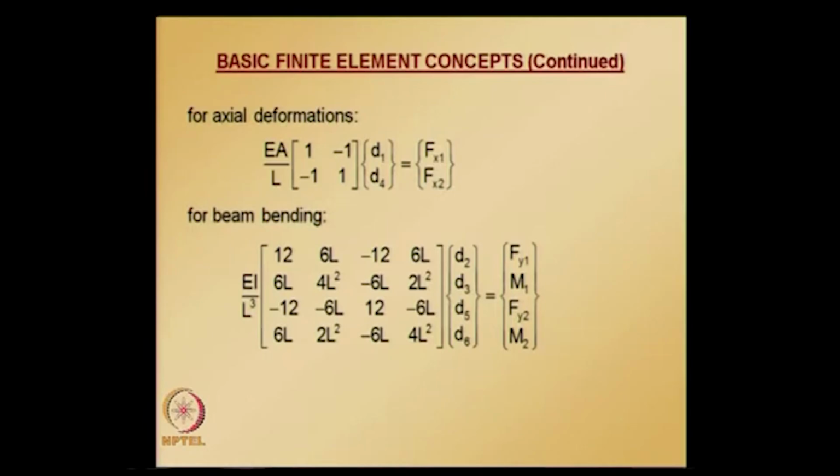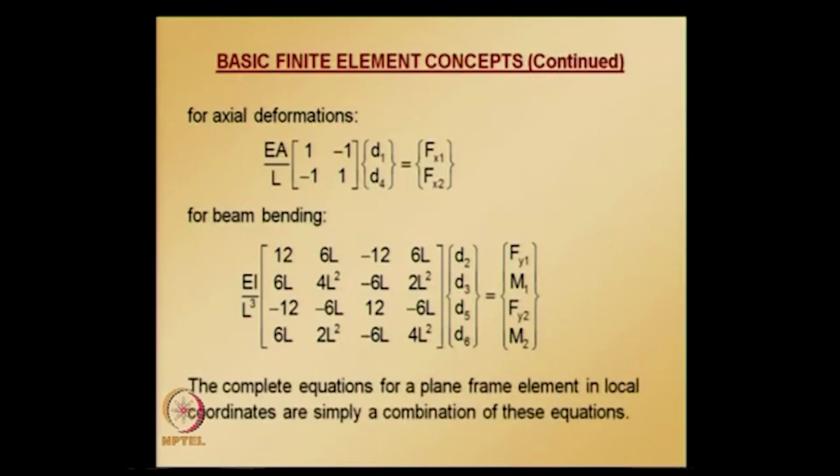We need to appropriately place the contributions from each of these two, axial deformation and beam bending, to get the complete element equation for the frame element in the local coordinate system, and that is what is shown here.